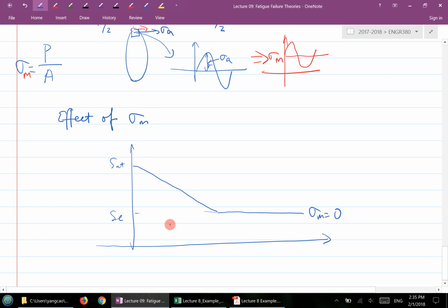If you recall, when we learned fatigue loading, there's one thing that we mentioned for the fracture propagation. Under what condition will this fracture propagate? Only when the stress is tensile stress, right? Only when you're stretching it will the fracture progress.